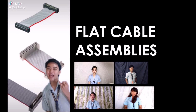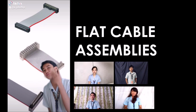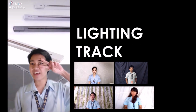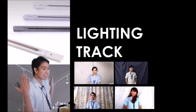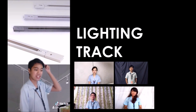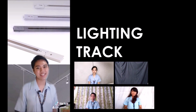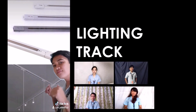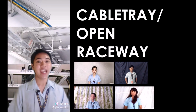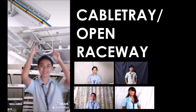Number 6. Flat cable assemblies. A structural channel designed to carry 2 to 4 conductors. Number 7. Lighting track. A channel with conductors for 1 to 4 circuits permanently installed in the track that will act as a light-duty plug-in busway. Number 8. Cable tray or open raceway, a continuous open support for approved cables.